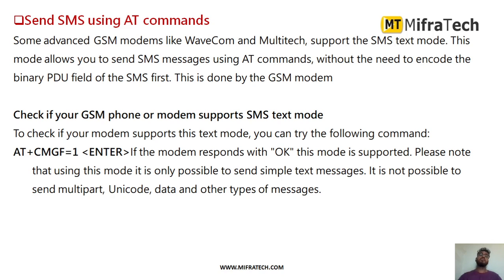Next we'll see how to send SMS using AT commands through this GSM module. Some advanced GSM modems like Wavecom or Multitech support SMS text mode also. This mode allows us to send SMS using AT commands without needing to encode the binary PDU field of the SMS first. We can directly do that.